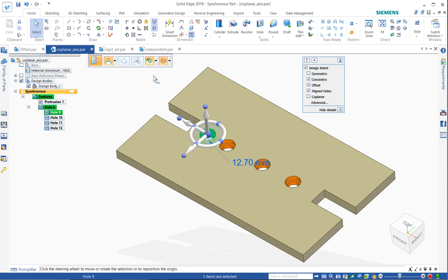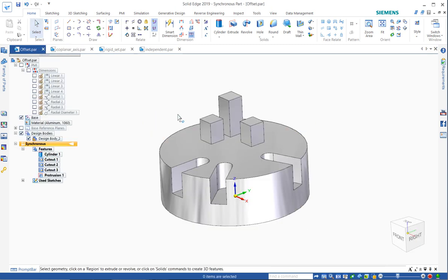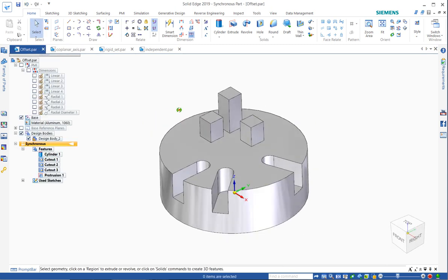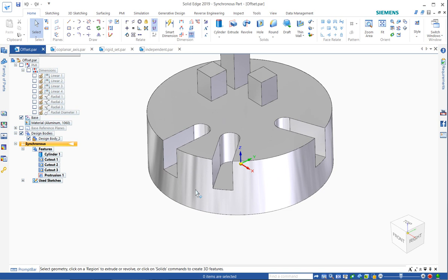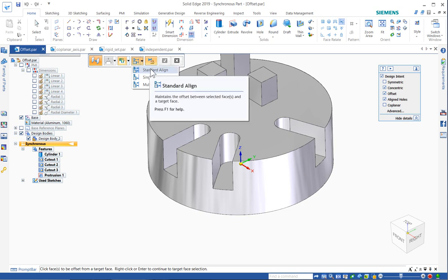And you have two options here. You can just pick something flat, and it will use a flat plane, or you can pick another point. So you see it picks up that vertex, and let's say those are a little bit skewed, so they would be lined up from the first hole to that vertex, or using a plane. And again, you would persist that if you wanted to, though I don't think you really need to with holes,